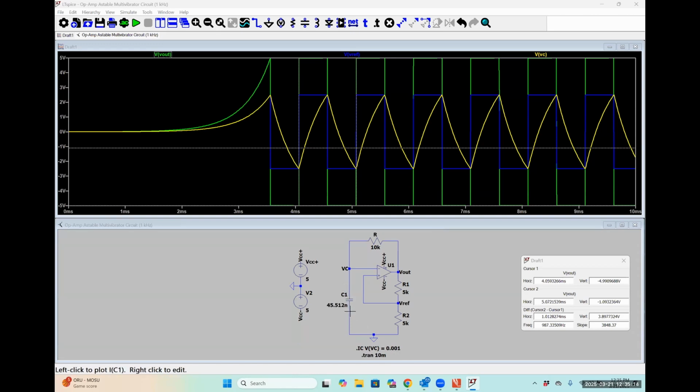So I gave my capacitor an initial voltage of 1 millivolt, which isn't an unreasonable amount of thermal energy stored in our capacitor. We all saw using our multimeters that we usually had a couple of millivolts of variance when measuring voltages across elements just due to thermal noise. So this is a realistic amount of energy that might be stored by a capacitor connected to a circuit. And within about 3.5 milliseconds, our transient has died out enough to where we just get our switching.